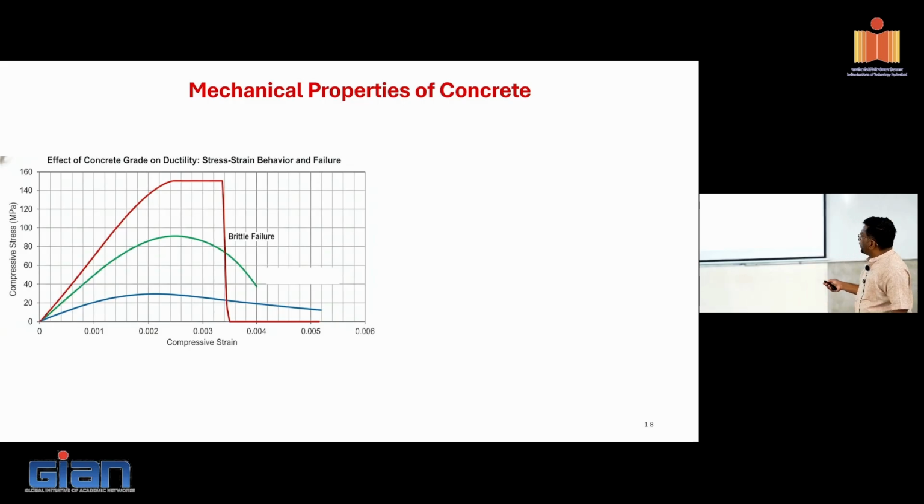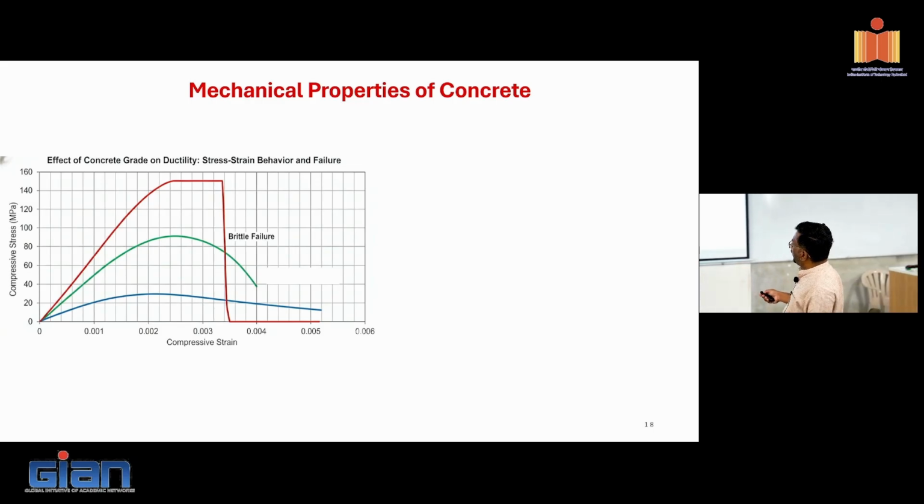If I have a lot of fibers, they are going to arrest that lateral cracking, that lateral tension that develops, and then the material is not going to give up very quickly. So it is going to behave in a more ductile fashion, like what you see here in the graph. Though I gain high strength, the material strength is not degrading quickly; it stretches up to a certain